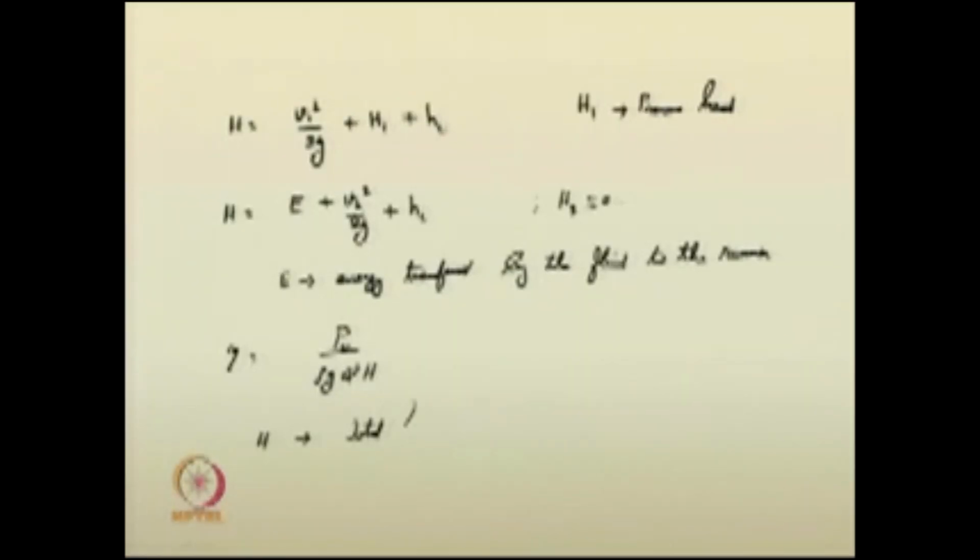Here we are using H, we are suggesting it as the total head available at the turbine inlet, that is the meaning here. So, eta is equal to P W by rho g Q, based on the total head available at the inlet, how much quantity you can efficiently use, that is the meaning here.